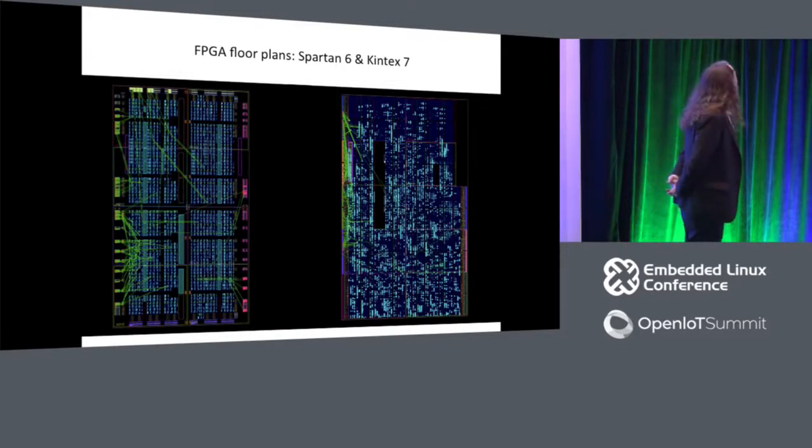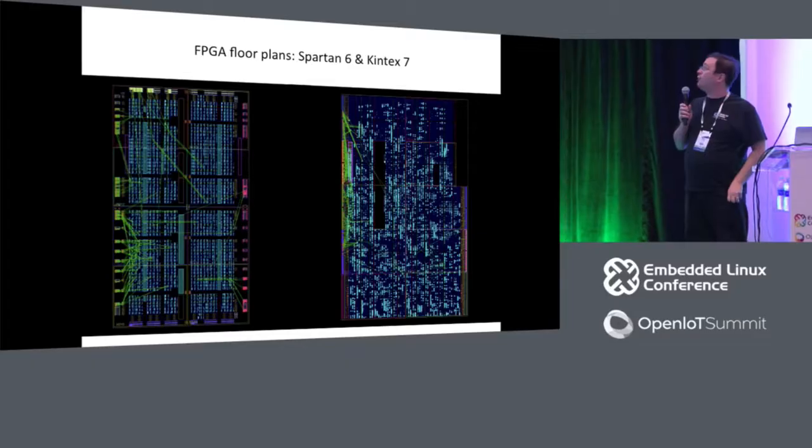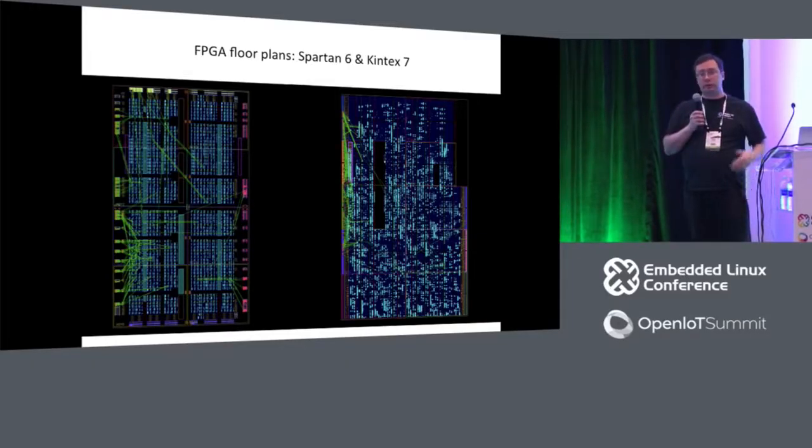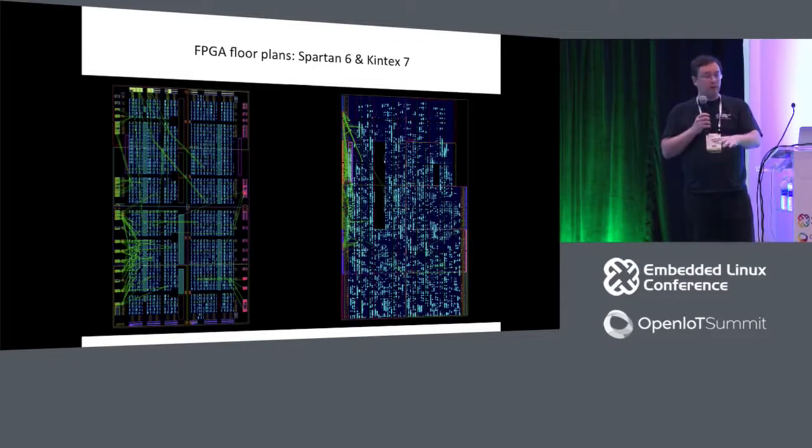Yeah. When he says that this is a $15 FPGA chip, that's if you're going to be shipping a device with an FPGA chip on it. Right. A development board built around this, the cheapest we found is the Numato Mimas V2, which is $49.95 from a company in India, plus shipping. We have a future slide on that, but it doesn't have Ethernet on it. It doesn't have enough gates to let you do an SMP implementation, only a single processor. That's a great intro board, but you're going to outgrow it.